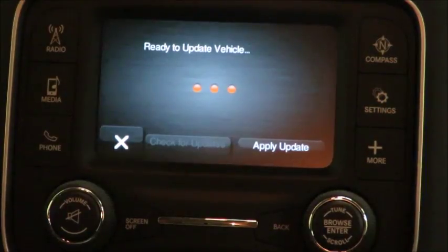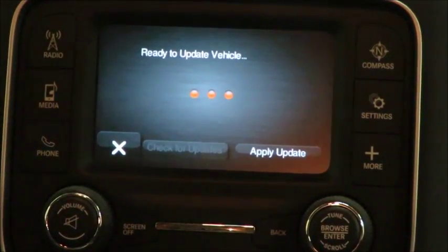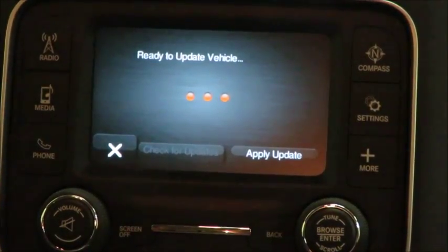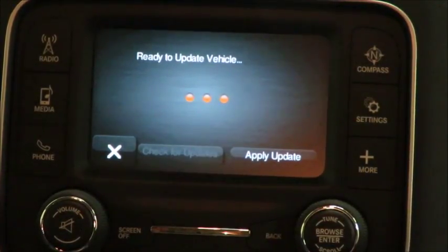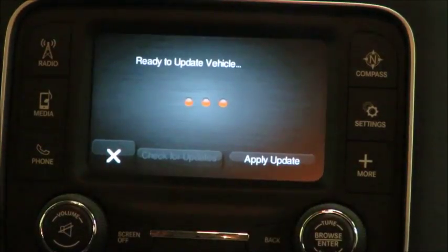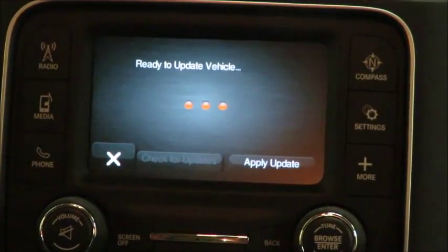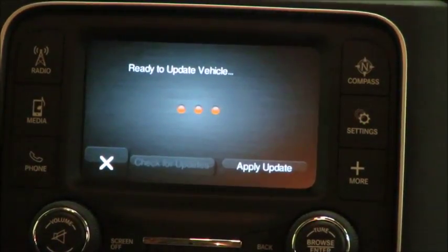This new inventory is sent to the OTA cloud, where an is versus should comparison is made, identifying any new updates configured for the vehicle. Both the necessary ECU module software and control files describing the installation order, pre or post condition, and procedures are downloaded to the vehicle. This allows the installation to occur while the vehicle is offline or disconnected.